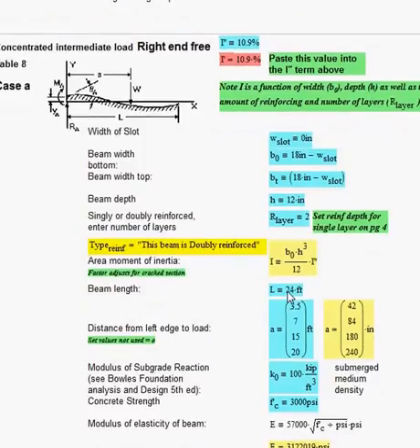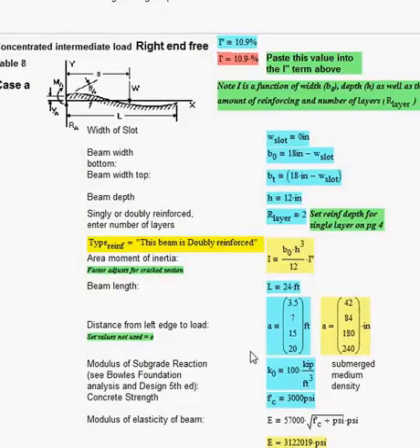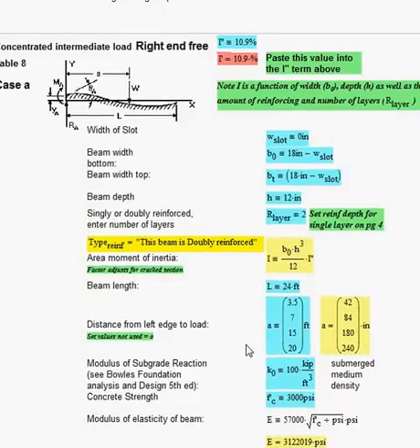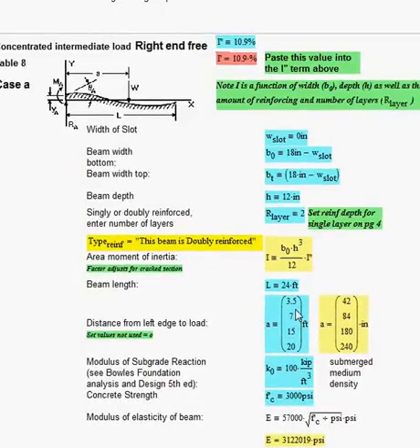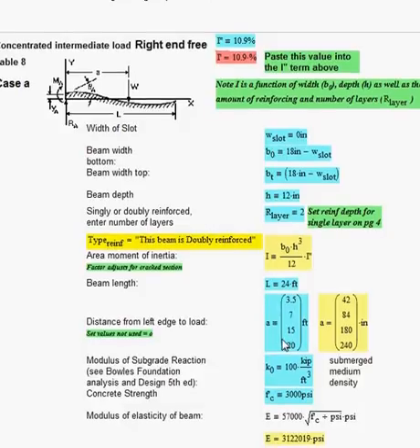The beam length is set, again, on this page. The load point distances are entered from the left end. Do not use distances greater than the beam length or you'll get an incorrect solution.